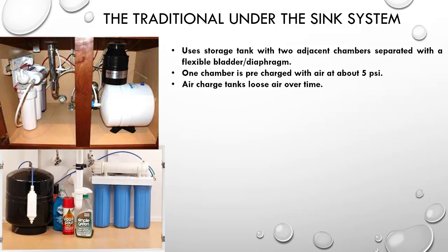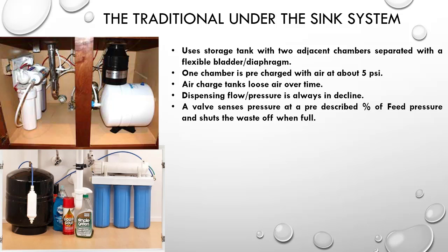One point to remember is that these air captive tanks do gradually start to decline in water pressure and flow as you draw water from the system, or in other words, empty the storage tank. So if you were filling a large pot for your pasta boiling, you would probably notice it. The auto shutoff is designed to shut off the incoming water supply when the tank pressure reaches a predetermined percentage of the feed water pressure. Typically these shutoffs are shutting off at around 60% of the incoming water pressure from the home.